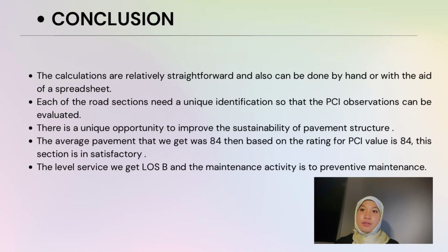For the last one, the conclusions. The method is relatively straightforward and can be done by hand or with the aid of a spreadsheet for the calculations of PCI. Each of the road sections needs a unique identification so that the PCI observations can be evaluated, and there is a unique opportunity to improve the sustainability of the pavement structure.